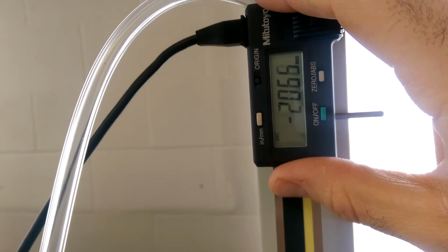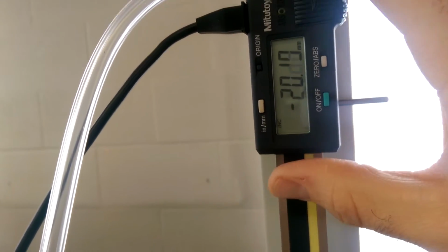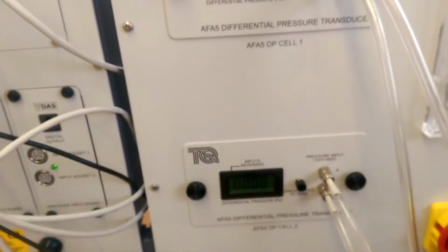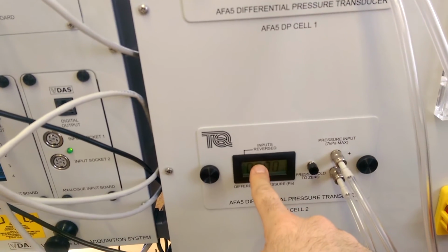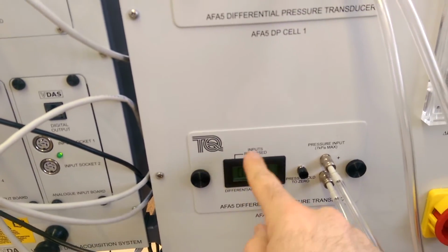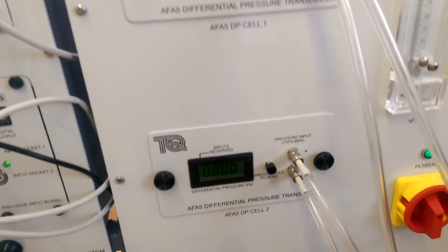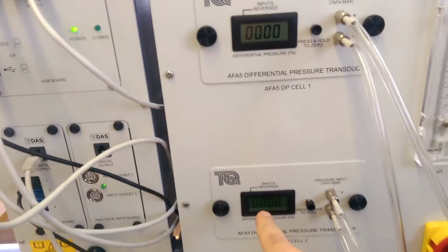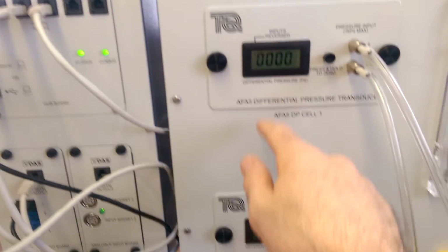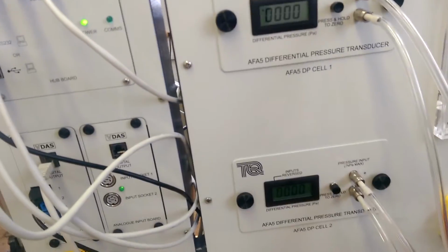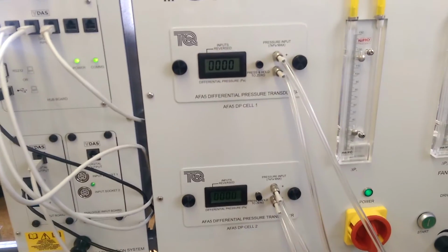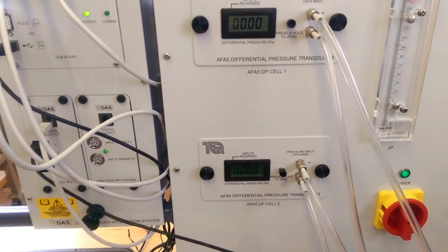And you're going to keep doing that every 10 millimeters. So then you'll come down to 20 millimeters. Do that, and then keep progressing. As you do that, you're going to see the pressure displayed at this manometer decrease, and then it'll start to increase again. Keep recording every 10 millimeters until this manometer displays a pressure that's approximately equal to that manometer again. It should be somewhere between 180 and 200 millimeters.